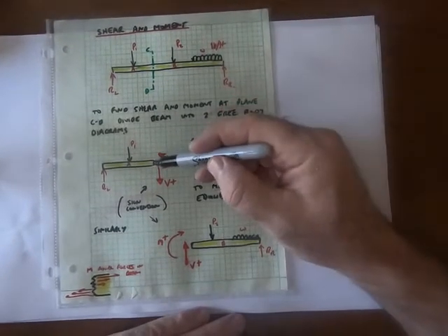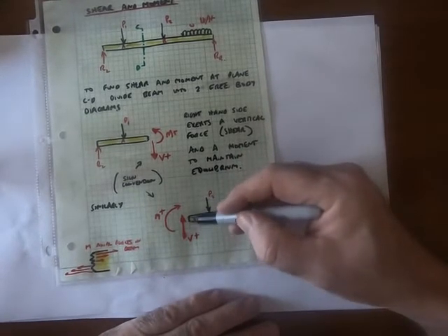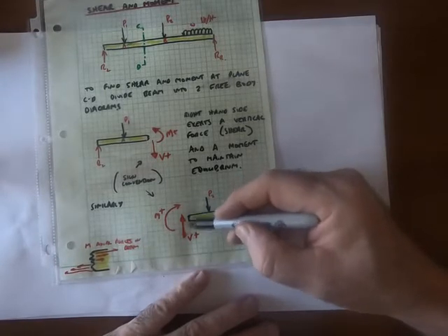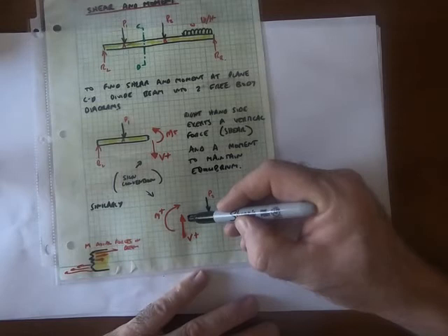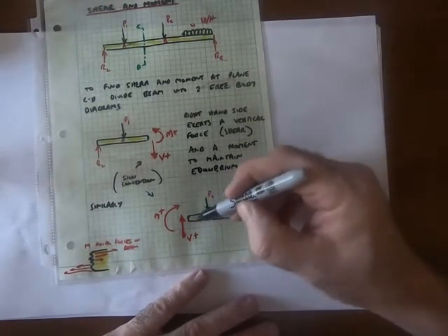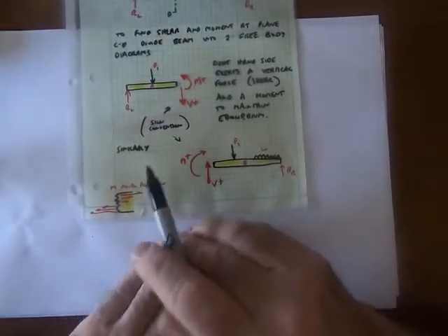what actually happens at the surface, I've just done a little sketch here. The shear force is obviously along the plane, it's in the plane and parallel to the plane. That force is spread over that plane. So the stress, the shear stress we call it, is spread over that plane. To generate a moment, we have forces that act perpendicular to that plane, and to get that moment they actually act in a way like this.